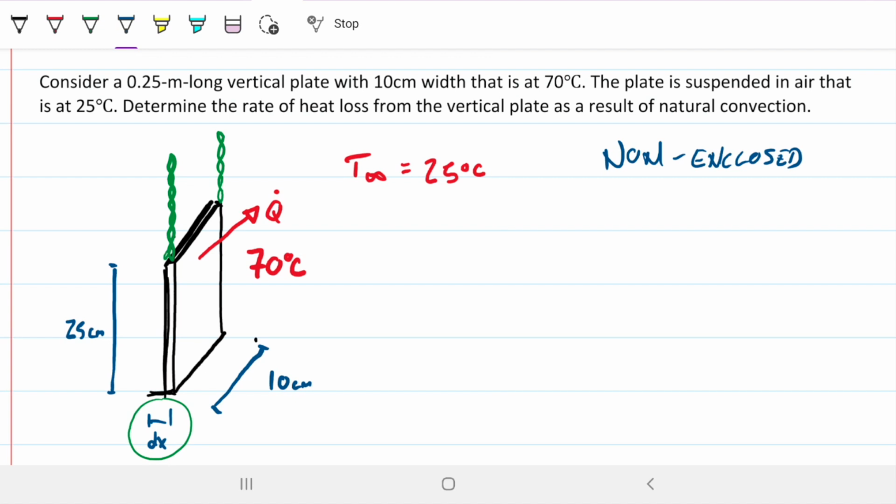So if that's the case, then our go-to correlation is Prandtl times Grashof, which is Rayleigh, to the m. What do we need to do to be able to solve this? We need to find what these are. The Prandtl I'll find by looking at a table. This is air, so I'll be looking at table A5 to grab the properties of air. The Grashof I'll be calculating by inputting gravity, beta, characteristic length, density, and viscosity.